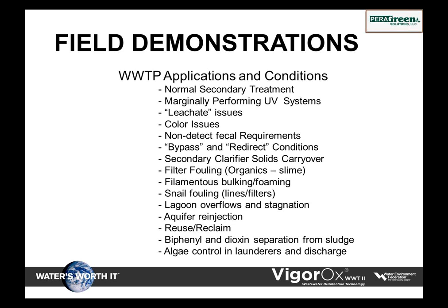Lagoon overflows and stagnation. This is key in some of the places in Missouri and small, 50,000 gallon per day facilities where they have lagoons. Stagnation is an issue. You have to understand what the components are, how it changes from day to day. So you have to be building that into your equation. Aquifer reinjection, that's pretty self-explanatory, a lot of work down in Florida. Reuse reclaim, a lot of the work that Solvay did was over in Italy and Milan, and that was primarily the use for the waters to spray it back on the crops.